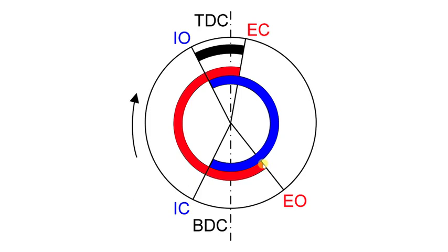The exhaust valve opens, and we push out the exhaust gas all the way as the piston comes up to top dead center. Then we start drawing air in around about here, and as the piston comes down again, we draw fresh air in, and the process repeats.